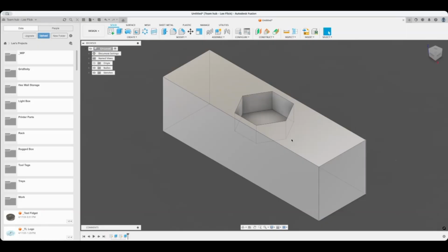Well, you have the box at least, right? Yeah. Okay. The next thing we're gonna do, it doesn't care about the hex. I just wanted to show that you can center a hex. You can make the dimensions so that as you change outer dimensions, it stays where you want. If you always want it 10 millimeters off the left side, you can do that.